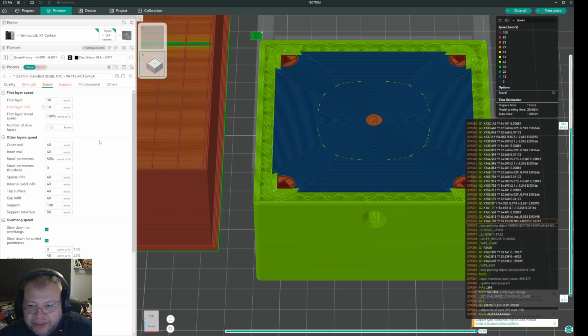Now there is another thing. If you print PLA too hot, it gets glossy or shiny, and how should I say it? It becomes smoother, and then you may have to compensate with lines in between, or like distance in the interface layer, but I wouldn't recommend that. I would just go down in temperature so it becomes more rough when you print it. So you keep it at zero distance in the interface layer, and you just print it a little bit cooler, so the lines don't flow so much sideways, because when you print the PETG, it will actually adhere to the micro gaps in the other filament.